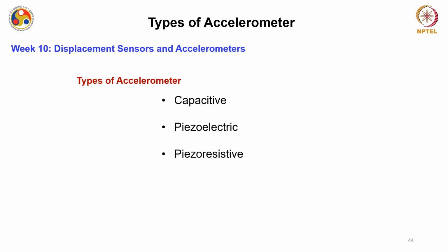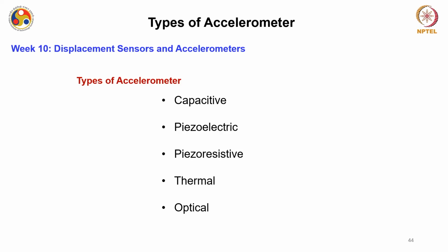We talked about a number of accelerometers which can be fabricated by MEMS and other technologies: capacitive devices, piezoelectric and piezoresistive devices, optical devices, and one more category, thermal accelerometers, where the proof mass was not a physical inertial mass as in all the other cases. Here the proof mass was the gas filled inside a MEMS cavity, so the gas itself was utilized as a proof mass. This segregates the thermal accelerometer from other kinds of accelerometers.